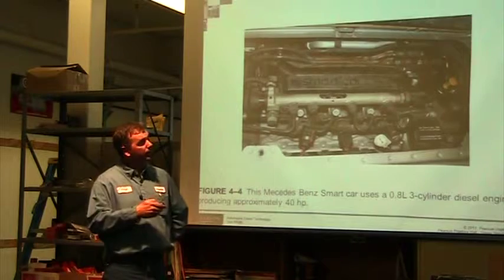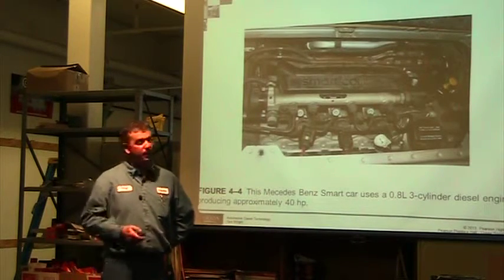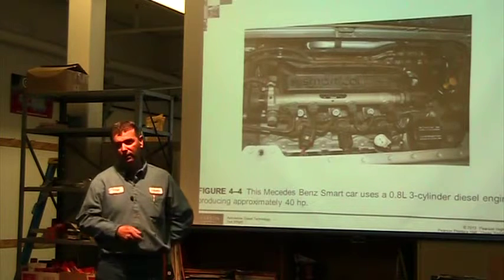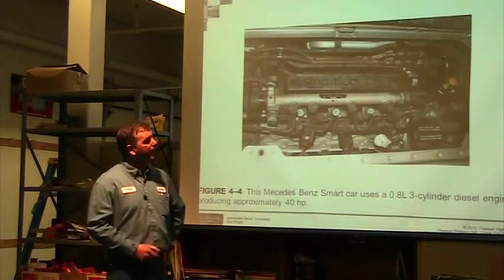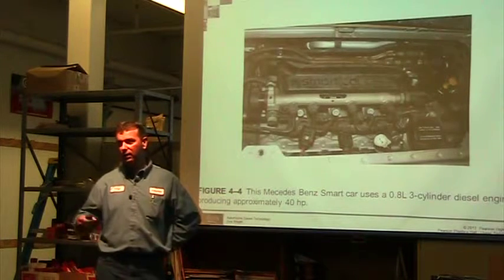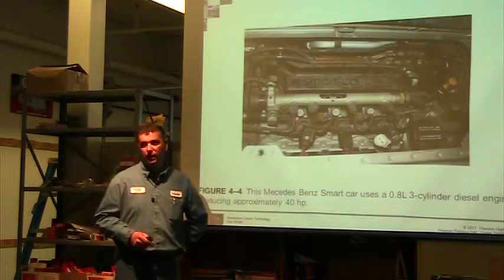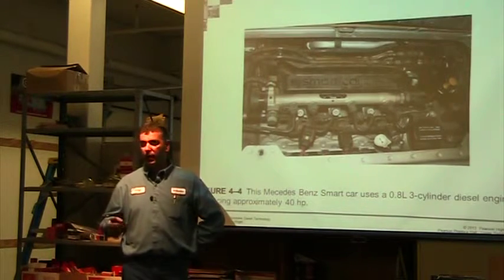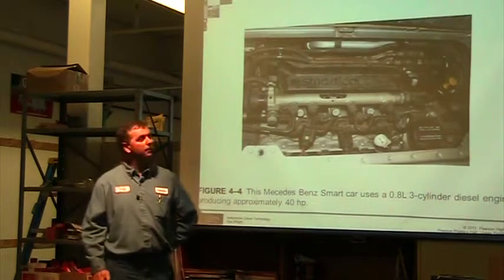I can't say that I've ever seen that on turf equipment, but it is a common thing in the automotive world. It's pretty easy to add as long as the fuel line you're going to use is definitely a fuel line. You don't just get clear water tubing and add it in there. There are some newer EPA compliant fuel lines that are clear that would lend themselves to this particular thing.